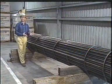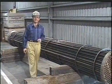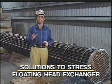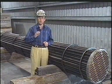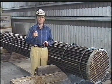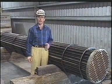A third type of exchanger is designed to allow both thermal expansion and easy maintenance. Because only one tube sheet is fixed while the other floats horizontally, this is called a floating head exchanger. The tubes are free to expand and contract in response to the temperature changes without stressing the joints. And the bundle and floating head can be removed for cleaning and inspection when necessary.